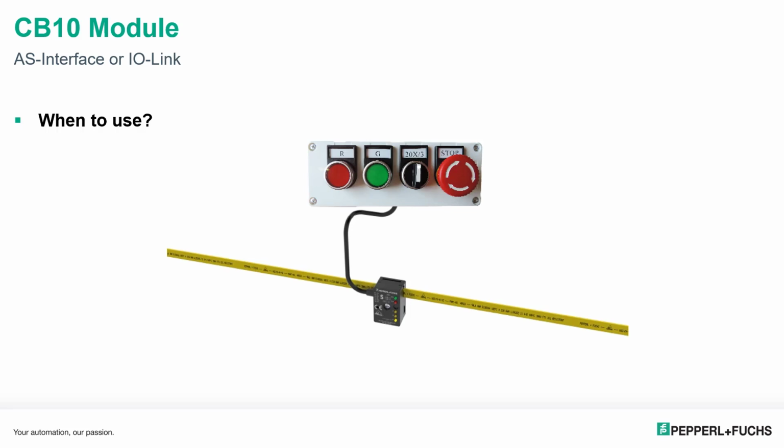And of course, when do we want to use IOLink? We want to use IOLink when we need high amounts of data at the sensor level. But we've got to be okay with point-to-point wiring, so think ring topology with 20-meter lengths. And you're going to need time to plan the layout, because you're going to have to order cables to specific lengths, and that includes cables for power as well. And it's not going to be so easy as it is on ASInterface to move stuff around in the future. IOLink does offer safety, but it's not currently as advanced as ASInterface is.